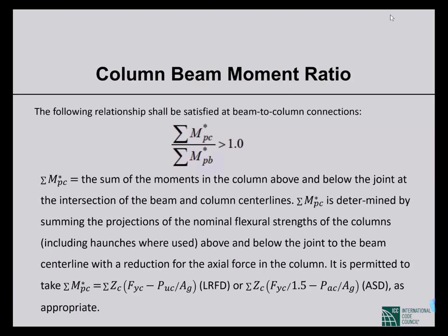When we actually calculate the capacity, we don't use those R's, reserve strength factors. But when we calculate the capacities of the attachments like connections, panel zones, then we consider the beam or the column to have not only Mp, plastic moment capacity, but multiplied by the reserve strength. Then we consider the reserve strength and we design the connections and the panel zones accordingly.